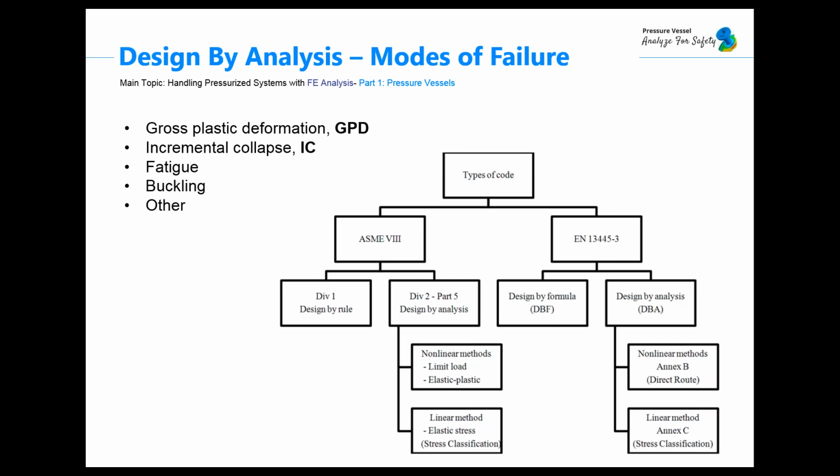It's not possible to provide equations for these areas. For example, if there are a lot of nozzles or other discontinuities, it becomes difficult to apply this approach without a big margin of safety. So this solution is sometimes not economical for complex designs.